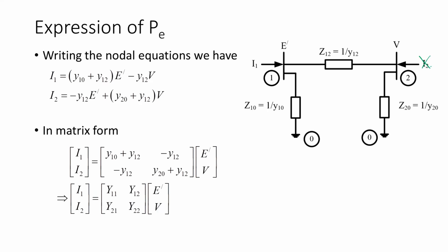Okay, so we forget about that. If I want to apply KCL in node number 1, so this is your I1. Let us assume over here I have got I dash. Over here I have got I double dash. So applying simple KCL, I can write that my I1 is actually I dash plus I double dash. So can someone tell me what is I dash equal to?